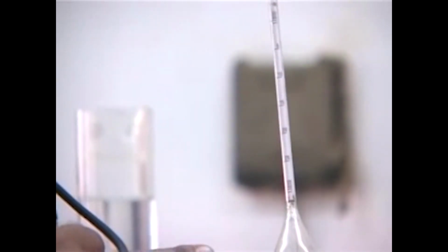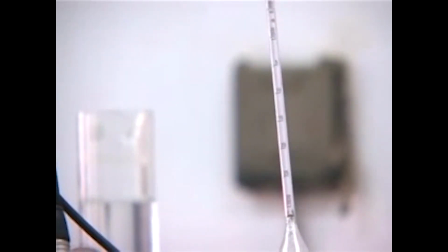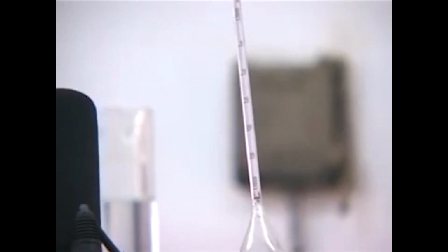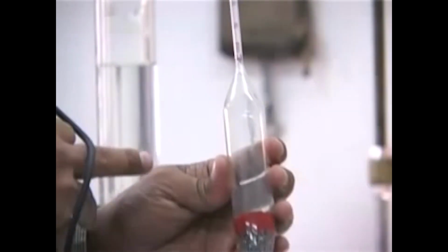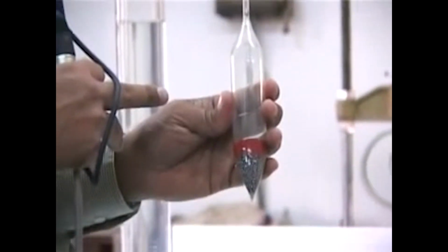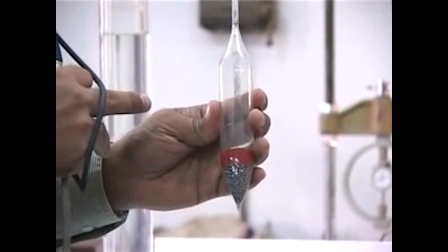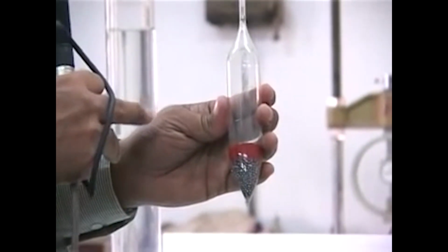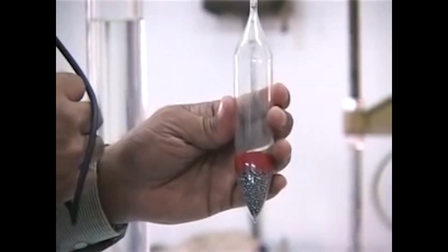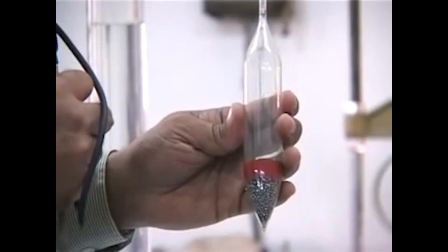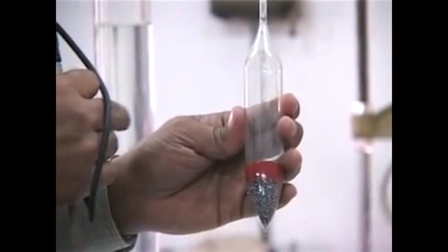And from that reading we can correlate to the specific gravity of the slurry at the center of the hydrometer bulb, and from that we can find out the representation of a certain grain size within the soil sample using Stokes' law of settling spheres, approximating the soil particles as settling spheres.